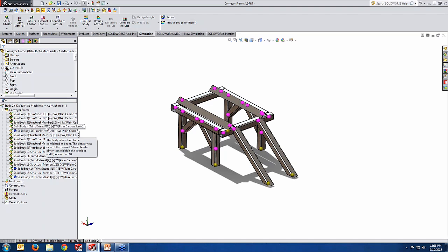The slenderness ratio of the beam, where the characteristic dimension, which is depth or width, is less than 10. There is a warning, and it can show you which component it is. Now, as a designer or analyst, you have a decision to accept a bit of inaccuracy at that point and change it to a solid or shell as you might like, or accept this and go ahead.